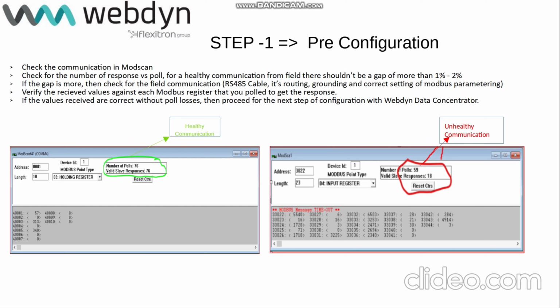That's why it's recommended, as per the standards also, to keep a sufficient distance between your communication cable and any other current carrying cables, a minimum of 300 mm, or 500 mm if possible, if you have to lay a communication cable in the same trench. And do remember to ground one end of the shield always, so that any interference coming from electromagnetic concerns gets to the ground immediately through the shield, and it should not impact much on your real data carrying core.